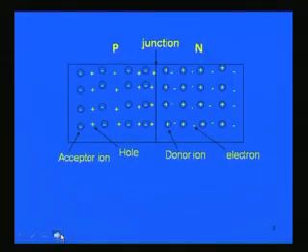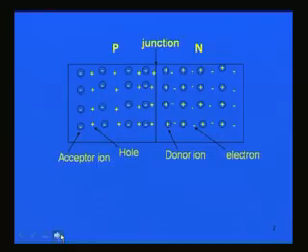When you have p and n type of semiconductors combined together by some appropriate scheme like ion implantation or diffusion, which, mind it, is not a mechanical process, so as not to disturb the crystalline structure of the silicon or germanium semiconductor, which is the base material. A properly formed p-n junction will have p-type on one side and n-type on the other side.